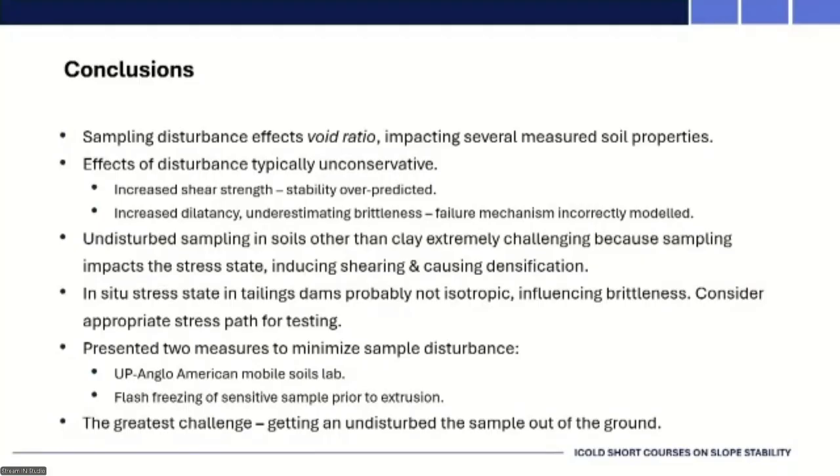The very act of pulling the sampler out, or the sample out of the ground, induces an amount of shear, an amount of densification. And the point that I want to make about in situ stress state is that in situ stress is probably not isotropic. And if it is not isotropic, how close is it to our instability locus or our critical state line? So it is important that we do not only worry about the state parameter, but also worry about the K0 value, so the in-situ stress ratio.